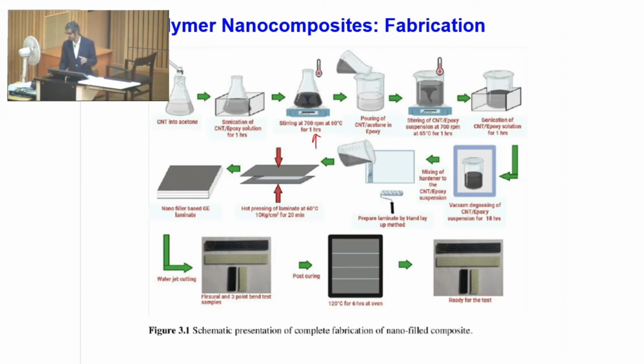So basically, the important aspect of this fabrication route is that this is a widely used fabrication route. You know that you have to mix them very well. Once you mix them properly, then you can pour into a container and vacuum degas. That is a widely used technique. Vacuum degassing is not a very difficult thing to understand. You can remove by vacuum degassing all the water and other impurities which are easily removable, and it will leave behind the solid composites. So that's something which is very routinely practiced in the real world or material world.